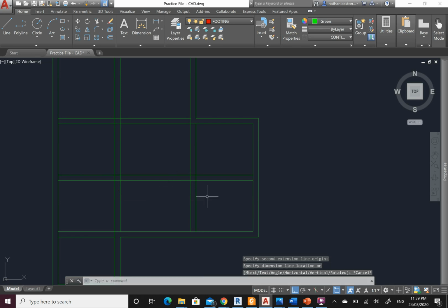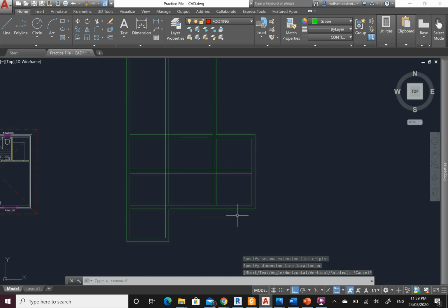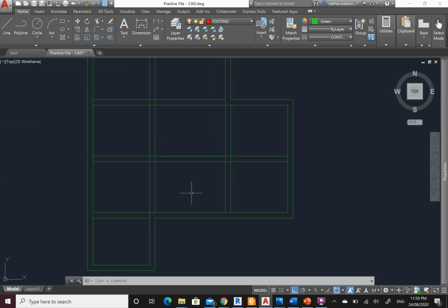Now this is where, when you come into geotechnical engineering, you'll be studying the standards and going through, but for now you have to take my word for it. That 4 meter center to center is for the first footing from an external. Okay, so from this way and from this way. So this direction, this is okay. This direction is too wide.